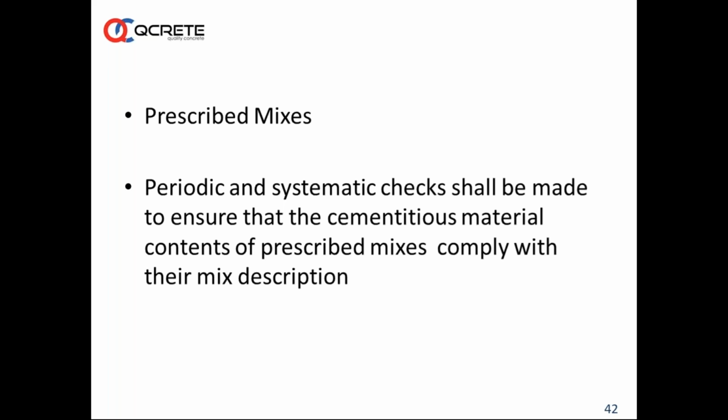On the other hand, you have prescribed mixes, where just like a medicine is prescribed by a doctor, the client will say, I want 400 kg cement, water cement ratio 0.39 or 0.44, and then you have 20 like this and all. This is called a prescribed mix. Here, what happens is he is tying the hands and legs of the ready mix company, concrete technologists, and many times such mixes will perform badly in terms of both fresh and hardened properties.